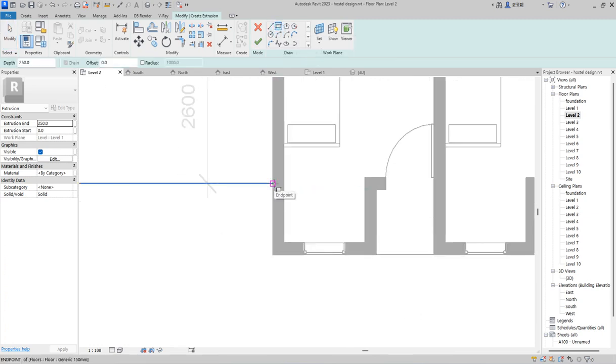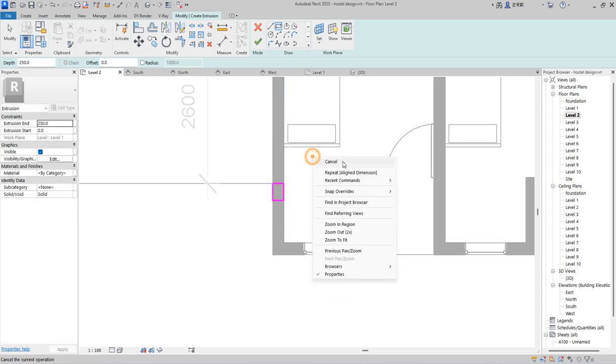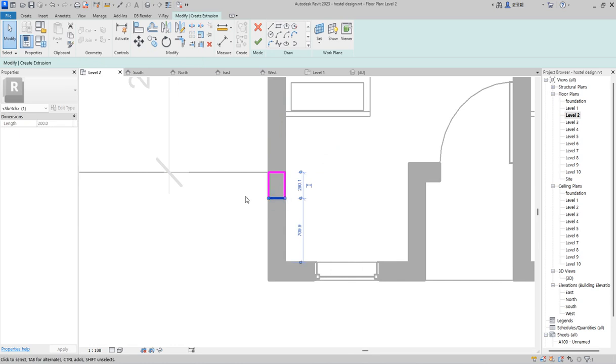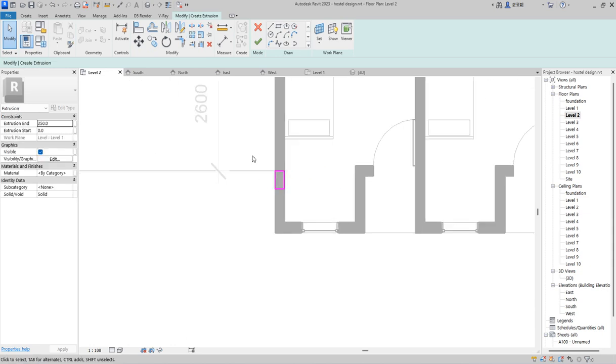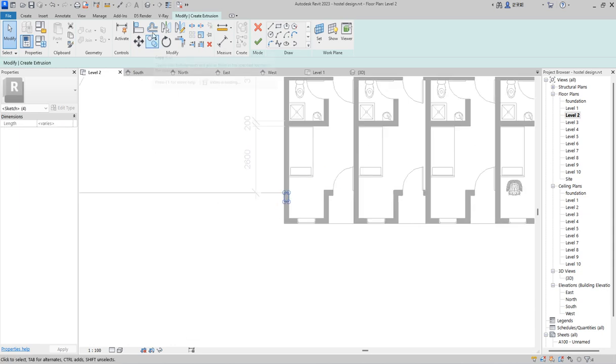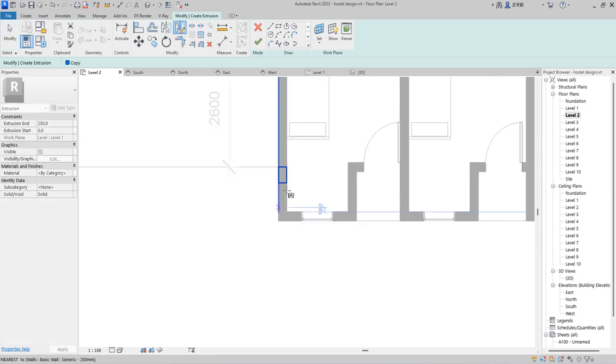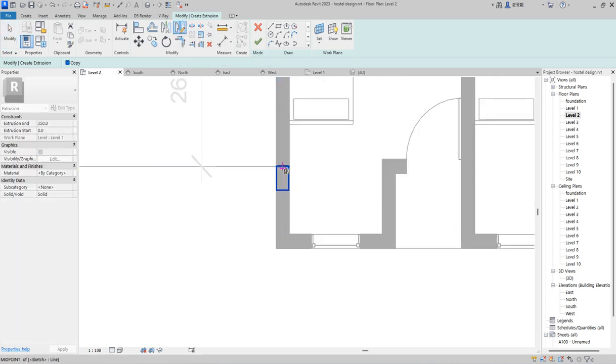Here, I'm going to use rectangular, and I put it here. It's a longer column I'm going to use so that we're able to support the base and the structure accurately. I will say 350 by 200 size, which is what I want to use here. Then I'm going to copy from here and start putting it where it's supposed to be.